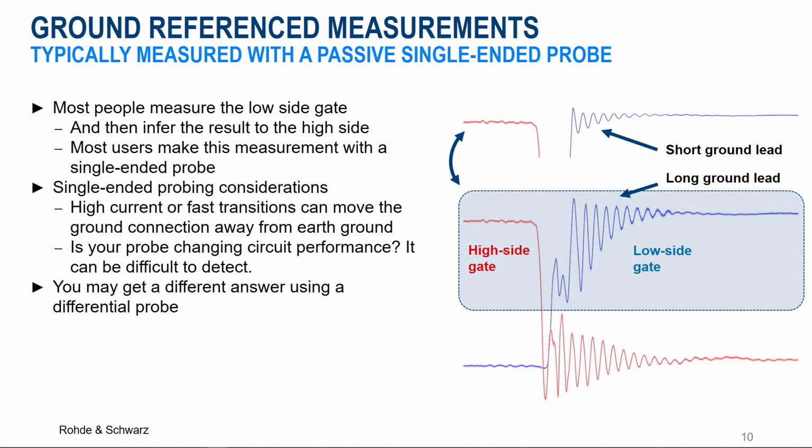When evaluating gate driver performance in a half-bridge design, most people measure at the low side and ignore the high side measurement, mostly because measuring at the low side is possible because it's ground referenced and not floating, which may introduce common mode issues. When you're measuring the low side gate driver, you're looking to ensure the design is meeting specifications and if it has the characteristic waveform shape. This characteristic shape can be established using simulation. Anticipating the waveform is important to compare measured versus desired results.